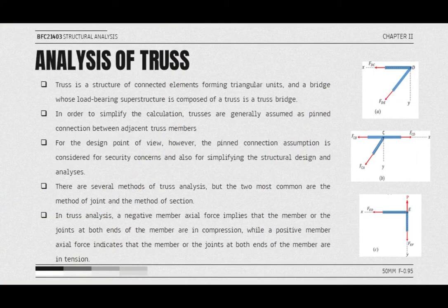A truss is a structure of connected elements forming triangular units, and a bridge whose load-bearing superstructure is composed of a truss is a truss bridge. In order to simplify the calculation, trusses are generally assumed to have pin connections between adjacent truss members. From the design point of view, however, the pin connection assumption is considered for security concerns and also for simplifying the structure design and analysis.